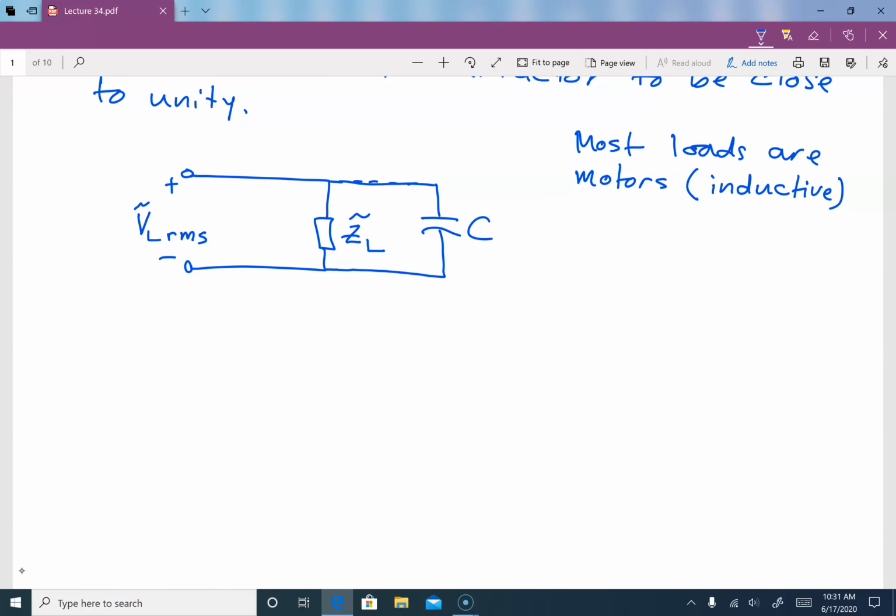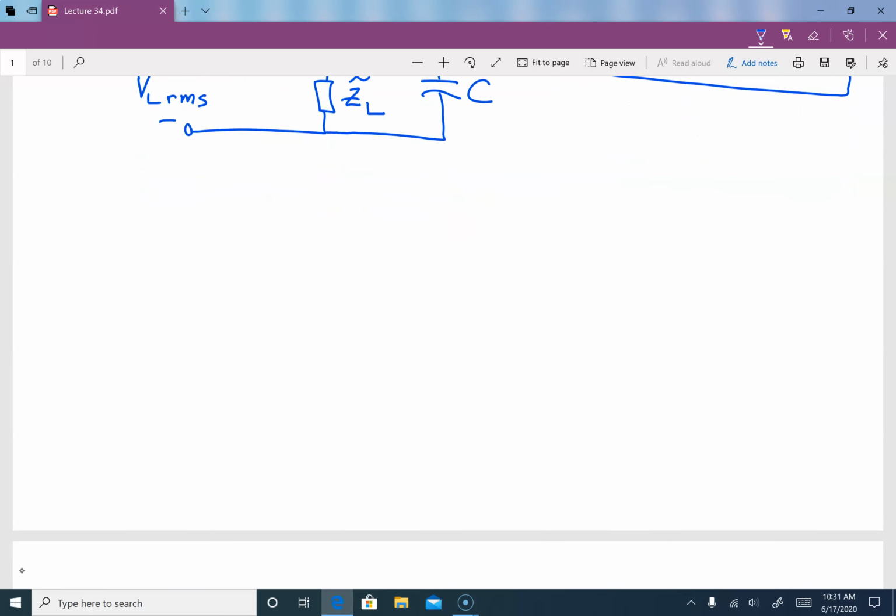So over here I would like everybody to understand this point, because the motor has windings, and these windings are coils, and since these are coils, that means they are inductances, which means that it is an inductive load. So the idea of power factor correction is like this.